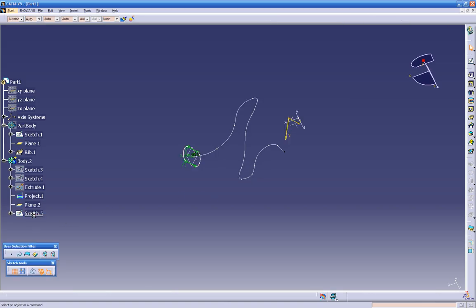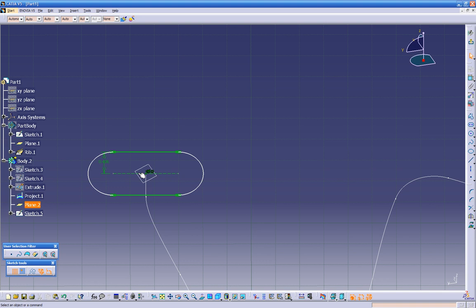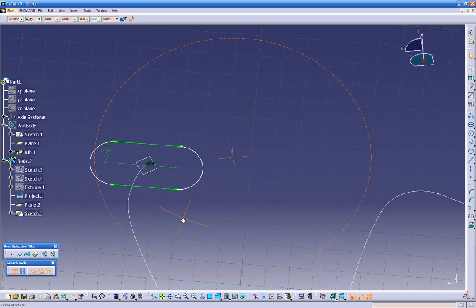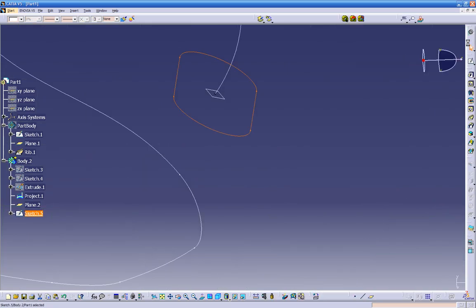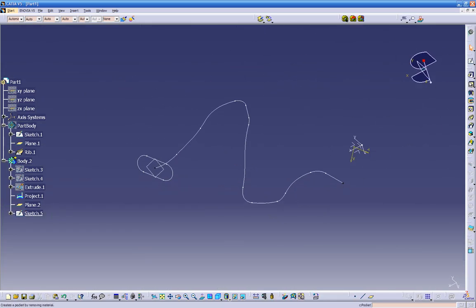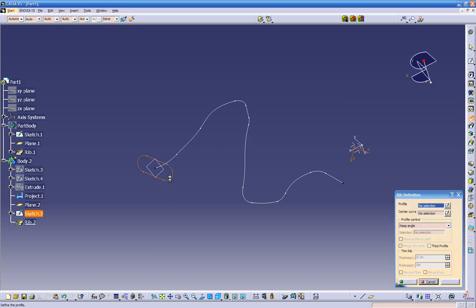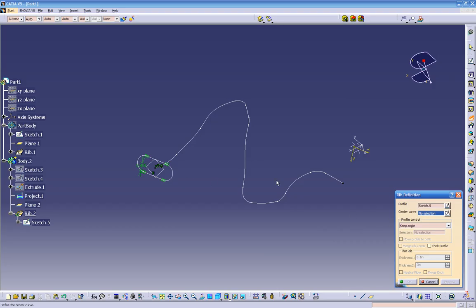Let's go back into our sketch, and I guess our point, I don't know how come I didn't pay attention, but this is not on. So my point in here is not set for the construction element. So just click on this. Now once I get out of the sketch, we don't see our point anymore. So now we can go back to the rib option, and we shouldn't get the error anymore. Click on the profile. Now click on the center curve.